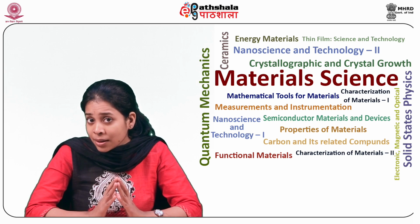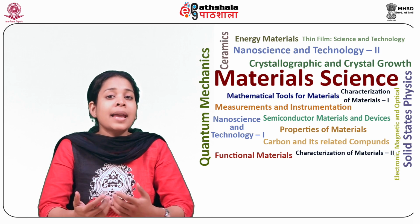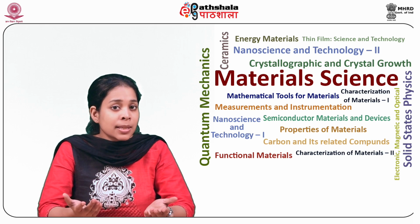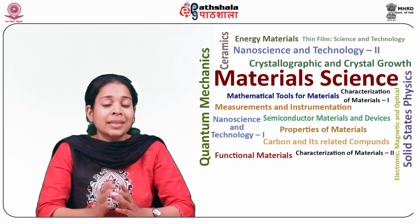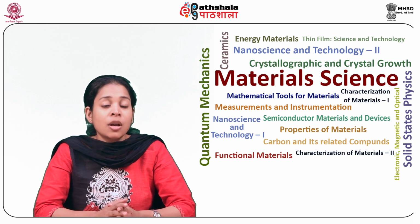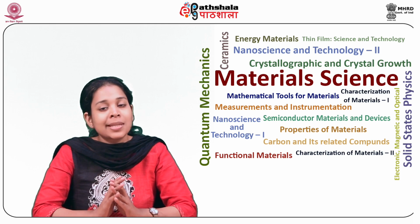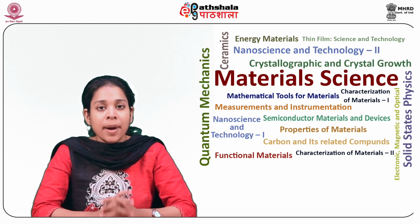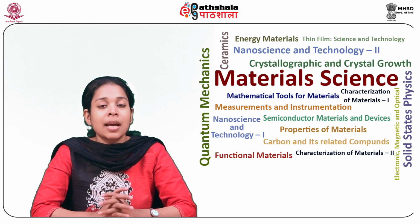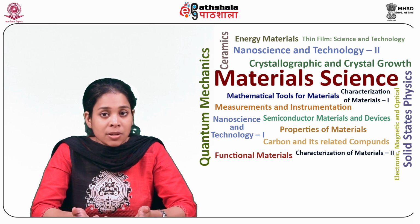As discussed earlier, the TEM mode is the transverse electric and magnetic mode, which exists in structures having two conductors surrounded by a dielectric medium. So the quasi-TEM mode is very much similar to the already discussed TEM mode, but it is present in microstrip resonators and coplanar waveguide resonators.